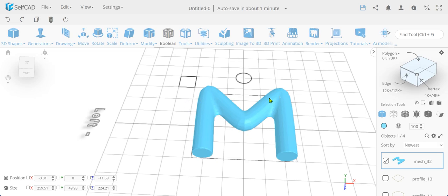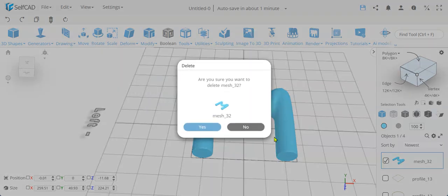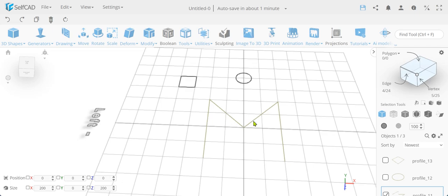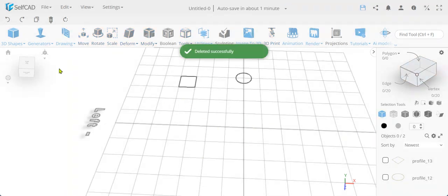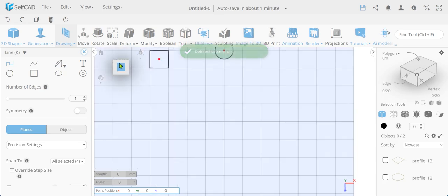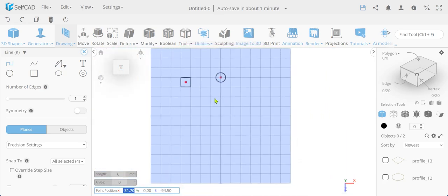If needed, you can also increase the smoothness of the original profile before performing the sweep, which will produce different results depending on the shape you're using. Solid Mode doesn't simply follow the profile exactly. Instead, it creates a smoother, spline-like interpretation of the geometry, producing a cleaner and more organic result. However, that's not even its biggest advantage.